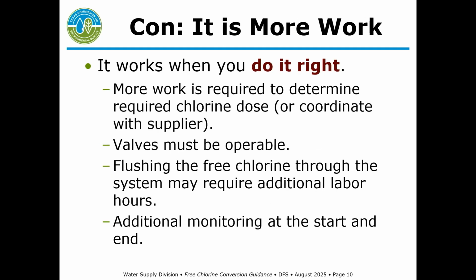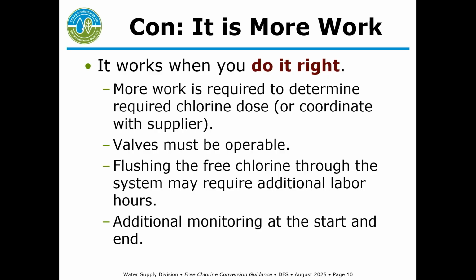So a con is it does take you and your staff more time to do a free chlorine conversion correctly. You need to do some work ahead of time to determine the required chlorine dose or coordinate with your supplier. You have to make sure all your valves and fire hydrants where you're flushing are all working. The actual flushing process that we'll go into in more detail does require more labor from your staff than would be normal. And then you have a bunch more monitoring both at the start and at the end.